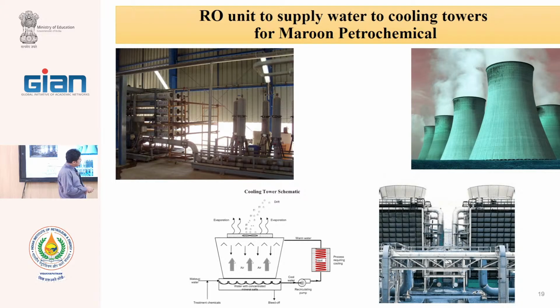In cooling towers the mechanism is simple. The water is poured from 50 meters, sprayed to the ground. During this pass, some of the water evaporates, and when it evaporates, it takes energy from the water, and this evaporation causes the reduction of the temperature.